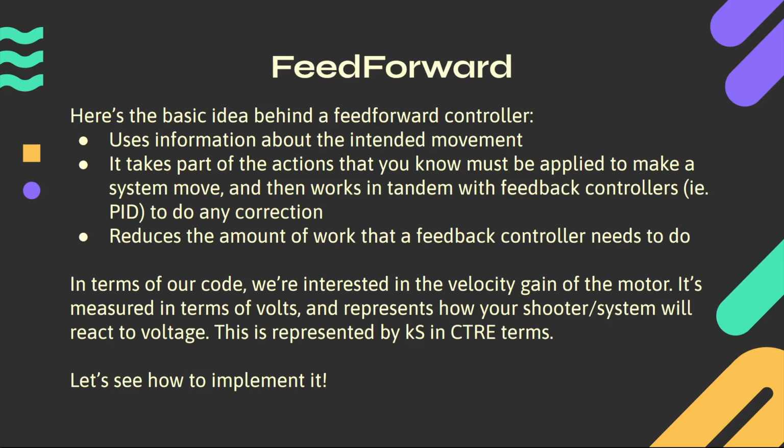In the absolute ideal situation, you rely only on PID to do micro corrections in your position or your velocity. I'm talking about a difference of 20 to 50 RPM within your goal is what PID would be responsible for, and feed forward is what gets you to that 20 to 50 RPM difference. So that's the idea.